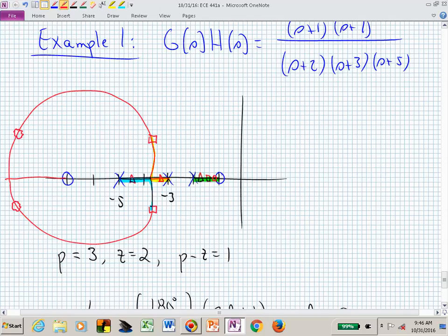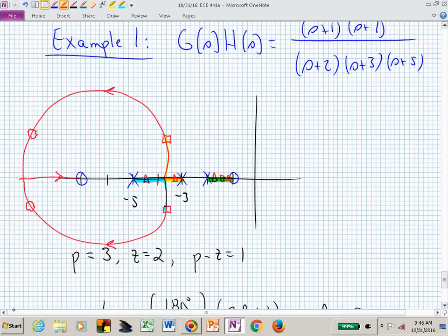Now, if I crank up the gain even more, what happens? These poles are going in this direction, but now these clouds are going to meet back on the real line. One's going to go here towards the finite zero at -7, and the other one is going to zip off to -infinity. Now if I use a different symbol, maybe now I have a star there. A star is off the page, but I'll just say it's in that direction. And another star is almost right on top of that 0.